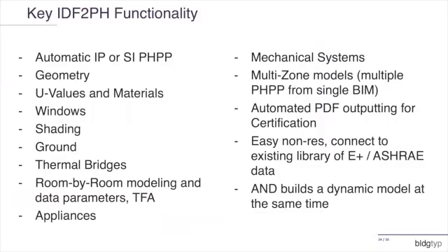Oh, and of course at the end of all of this you get that Energy Plus model at the same time, and it matches the PHPP. So I like that a lot. So then you can go off and execute your simulation in Energy Plus at any point. If you want to do a localized thermal comfort assessment, or an overheating risk assessment for a critical room or something like that, you can absolutely go off and do that at any point because you have that matching Energy Plus model.